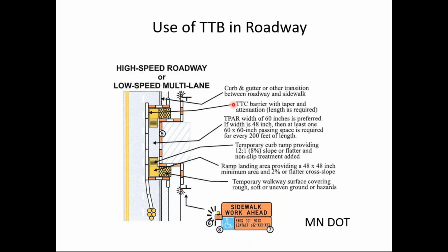And I think someone asked yesterday, maybe, do we need detectable warnings at the base of ramps? And the answer is the detectable warnings are needed only if the curb is missing at a street crossing. If there's no conflict with vehicles, you don't need detectable warnings at the base of the ramp.